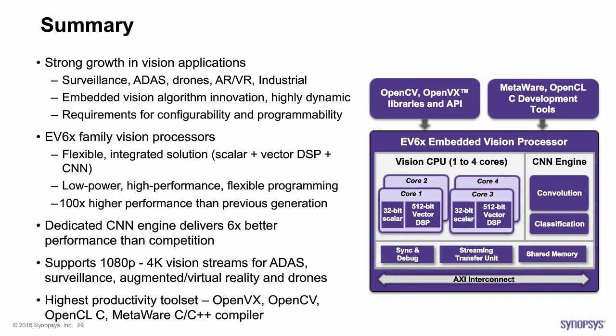All right, Mike, we'll move on to the next one. We've got quite a few here for you. Can I add APEX instructions to the EV processors? That's a good question. The APEX instructions are a capability that exists with the ARC processors that allow the user to add their proprietary hardware to the processor pipeline and add an instruction to execute that hardware, and that hardware can be blocking or non-blocking. It can be whatever you want. It's actually a very efficient interface that's fully registered. And that does exist for the vision processors. So, yes, you can add your own custom instructions.